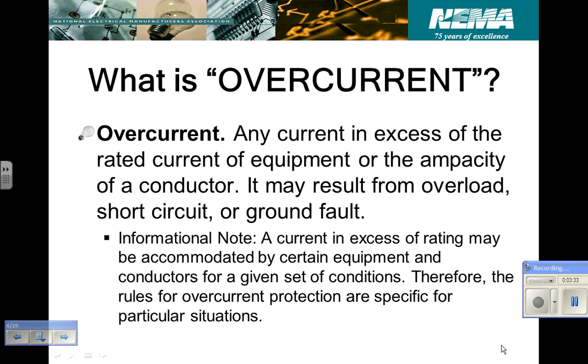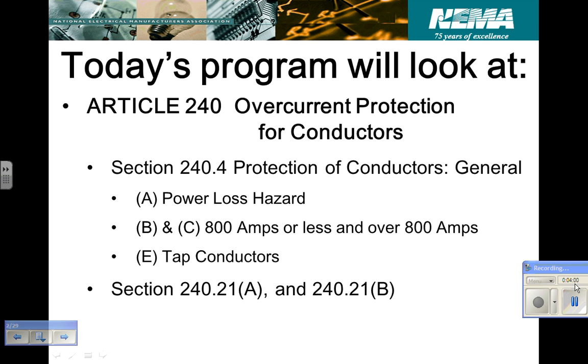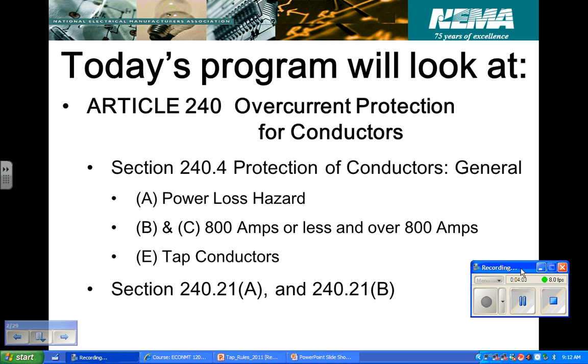And usually it'll be a fairly small current because the resistance will be fairly high. The minimum resistance for ground rods to the earth is about 25 ohms, and that's enough resistance to limit a circuit so that the amperage goes down, right? If you have a 120 volt circuit with 25 ohms, what is your total current? Around 5 amps. Okay, we'll go with that. If you've got a 15 or a 20 amp breaker and it's loaded at 5 amps, when is it going to turn the circuit off? Never. That's why ground faults are so dangerous.